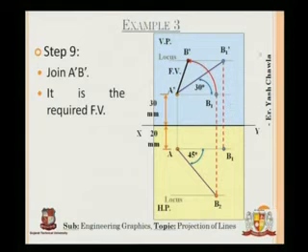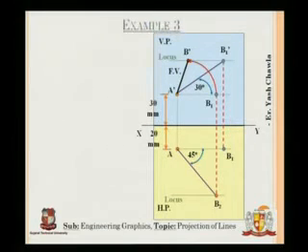So I already had my length, that is my elevation length. Now, for getting the angle at which it is present on the vertical plane, I drew this arc and it intersected this locus from B1 at B dash. So A dash B dash is what I got. Now I will do the same thing for the plan also.